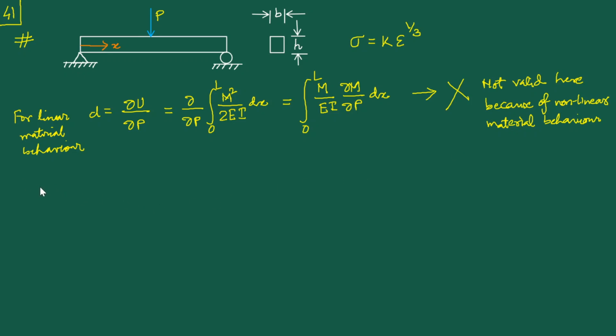Towards that end, first of all, note the expression for this M. We can start from scratch, from the understanding that the bending moment is basically a manifestation of the forces that are induced or connected with this sigma xx, and we directly use the geometry that we have for our problem here.